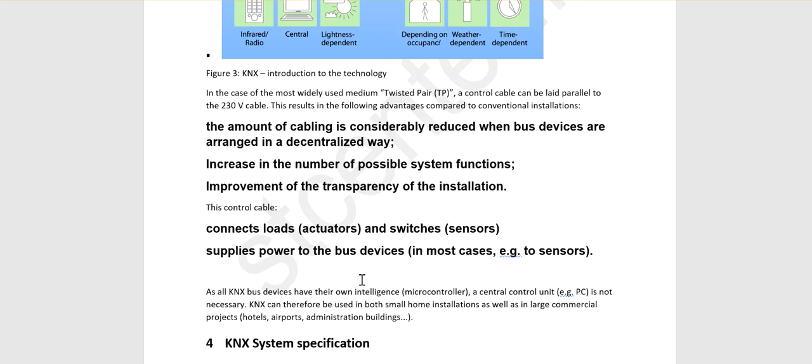Okay, this green cable, the KNX green cable, connects the actuators, sensors and controllers, so it sends and receives data over this cable, and it powers up the bus coupling unit for each device with a voltage between 21 to 29 volt DC. Yes, so you use a pair of wires, I mean the red and black in the cover of the green, to send and receive data and power up the KNX devices.